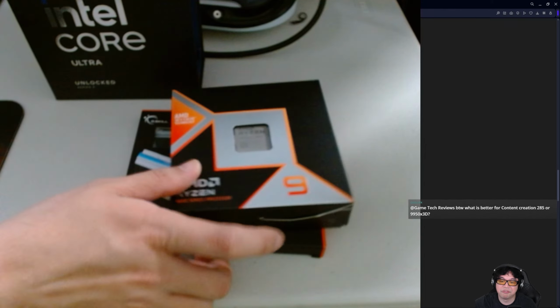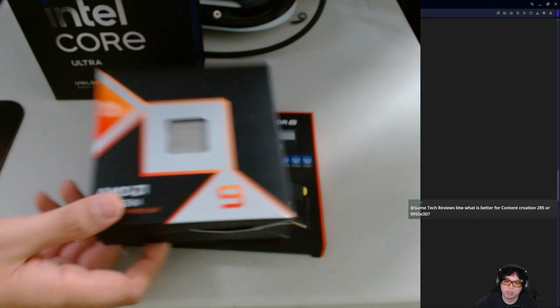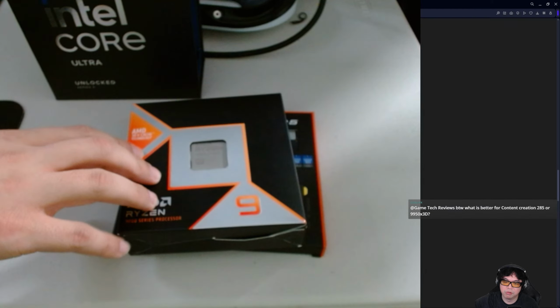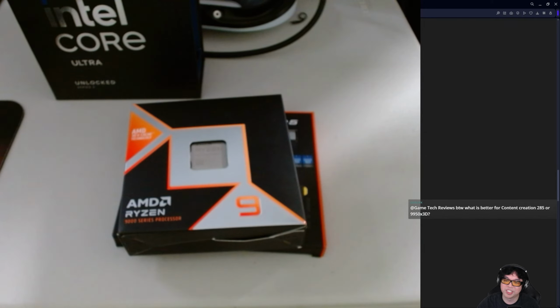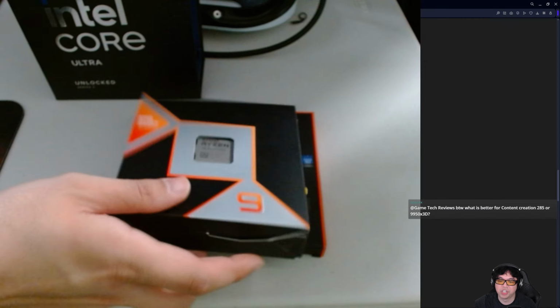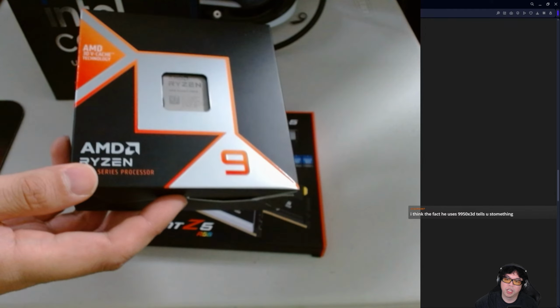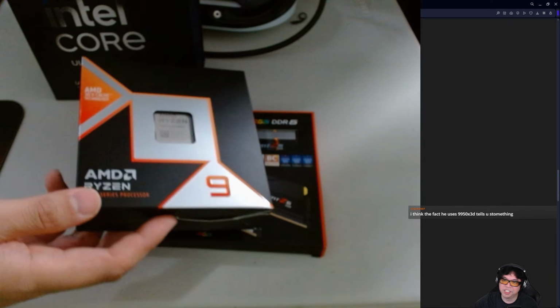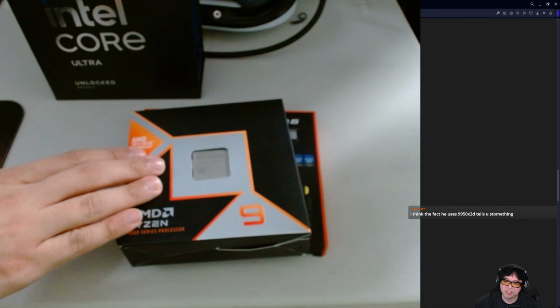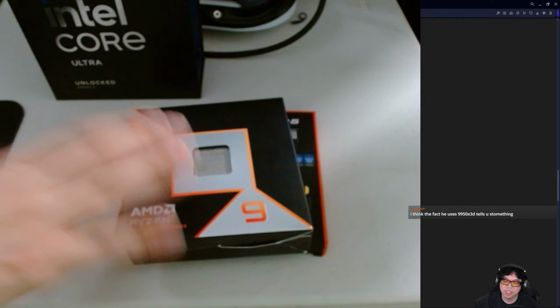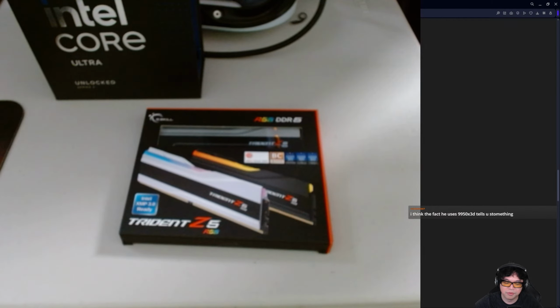But the AMD is very strong with the memory controller. So you can reliably do 8,000 with a good motherboard. You can reliably do 4 sticks at 6,000. We have many videos on the channel showing how to run 192 gigs, 128 gigs, a 96 gig single rank, all that good stuff. 4 sticks. You want 4 sticks DDR5? You go AMD. You want 4 sticks Intel?